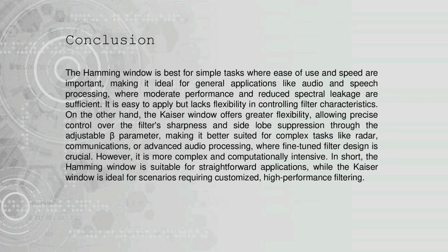Lastly, the conclusion is that the Hamming window is best for simple tasks where ease of use and speed are important, making it ideal for general applications like audio and speech processing, where moderate performance and reduced spectral leakage are sufficient. It is easy to apply but lacks flexibility in controlling filter characteristics.